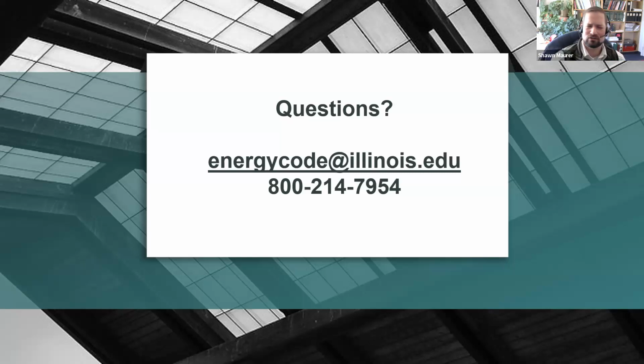We did have one question on clarification of controlled receptacles. In the 2021 IECC, it's now aligned with ASHRAE 90.1, which has had controlled receptacles in it for a while. But 50% of the receptacles in a commercial space need to be controlled by an automated system. It could be time clocks, occupant sensing controls, or load sensing controls, but something that turns off 50% of those receptacles, switching off unnecessary equipment that's plugged into them to minimize plug loads in buildings. So that's what the controlled receptacles is referring to.